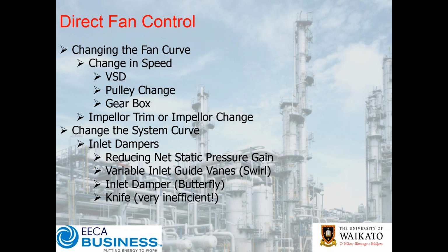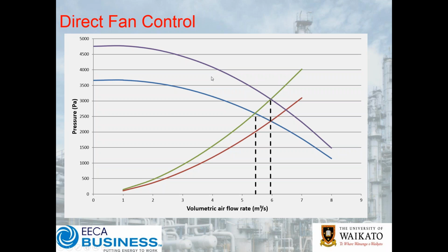Yeah, so noise becomes an issue as you disturb the flow. Then of course it can also be a source of vibration, and air ducts in particular tend to be quite large and often they're not as structurally rigid as you might like. The consequence of that is, if you disturb the flow, it has a really good ability to excite large flat sheets of ductwork. And so that can not only create noise from disturbing the flow, but then can create a lot of vibration that can cause and lead to other problems. So no, very good question.